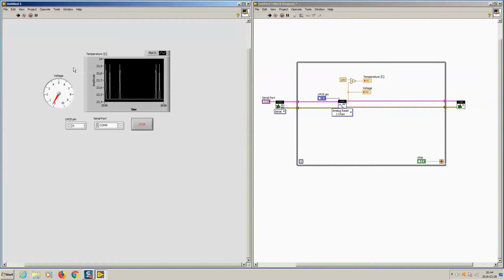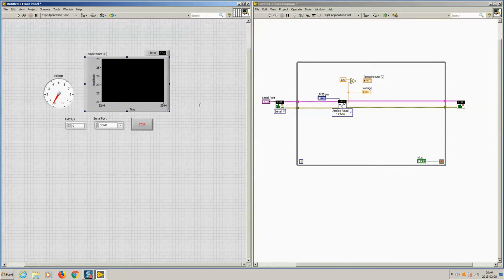In addition to analog inputs, digital input-outputs and PWM outputs, Arduino is equipped with I2C, SPI and serial port peripherals. To demonstrate the way of communication through the bus, we create a program that reads the pressure value from the LPS331 sensor.